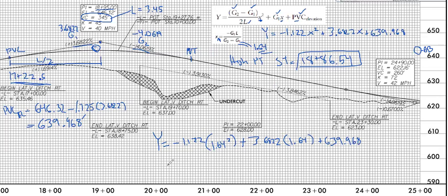So it's this. Now we can find the high point elevation. So just working that math out, we're going to find an elevation of 642.99 feet. And so that's the other component we were asked for, the station and elevation of the high point. And it tracks, it does work out. 642.99 is right around what we expected of 643 that we're able to read off the graph.